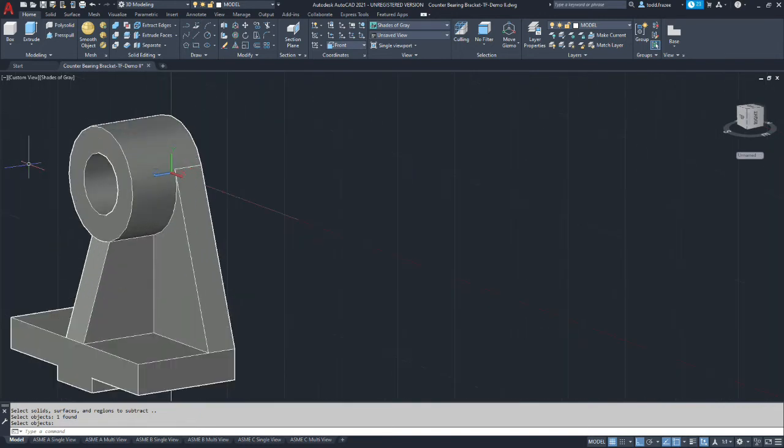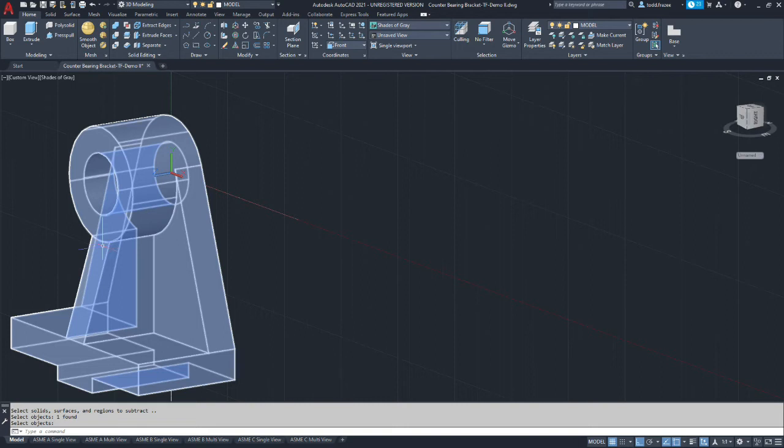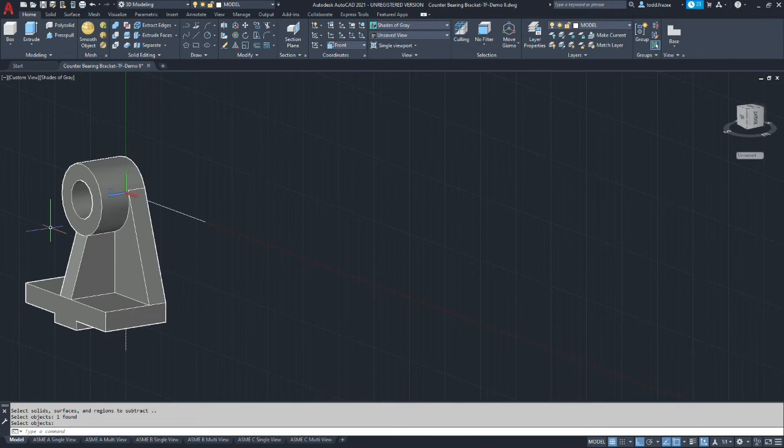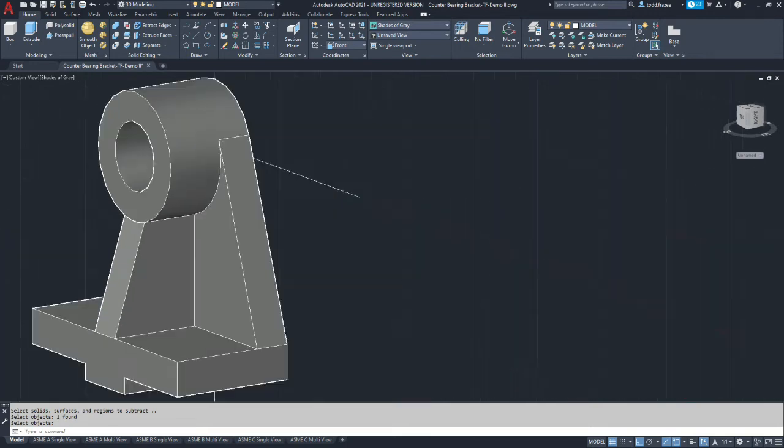The drawing is ambiguous, so it could be recessed with a partial fillet there. That would be one way to interpret, but without them giving us a dimension for an angle on this drawing, that little transition's up to interpretation.